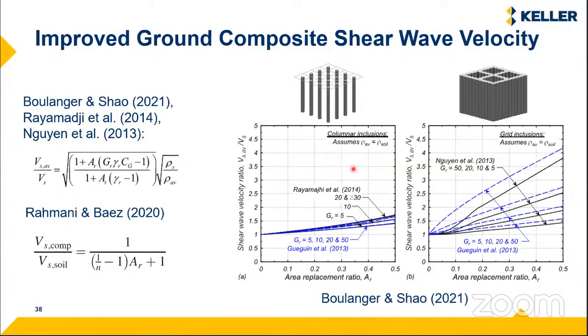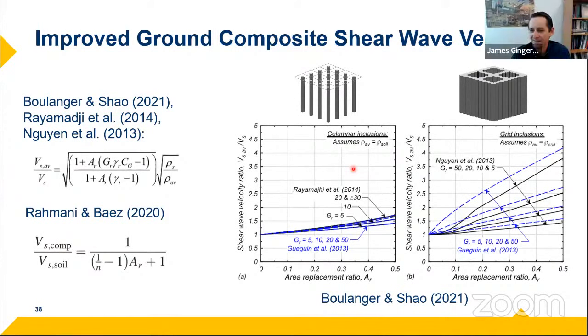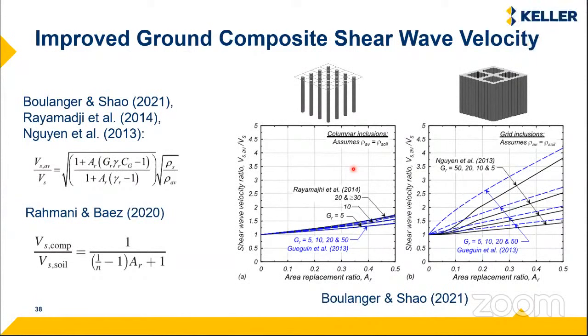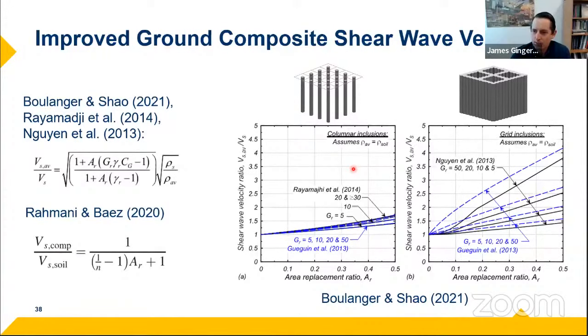Okay, our next question is, what is the best and most robust constitutive model for liquefaction modeling in numerical methods? That's a pretty loaded question. For me personally, the ones that I see used in practice the most are, I think PM4 sand has become probably the most widely used and popular. The UBC sand model is used a lot. The URS model is still used a lot.